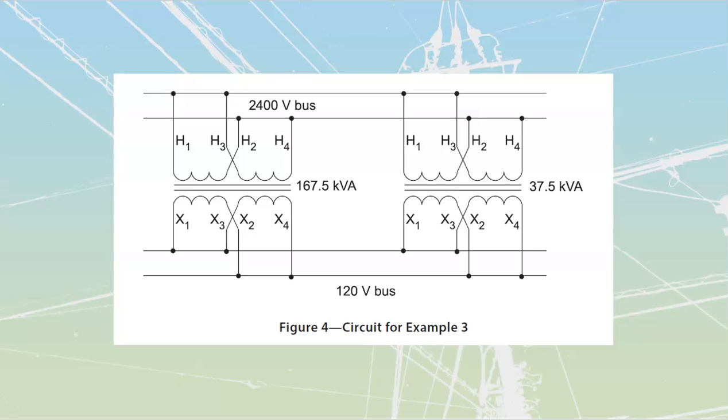These ones over here are going to be done properly. Obviously, if we're connecting a transformer that is 2400/4800, and it's a 2400 volt bus like we have over here, we would have to choose a parallel connection for that. So if I take a look at that, I see that all of the odds for both of these transformers are connected to line 1, and all of the evens, for both of these transformers, are connected to line 2.